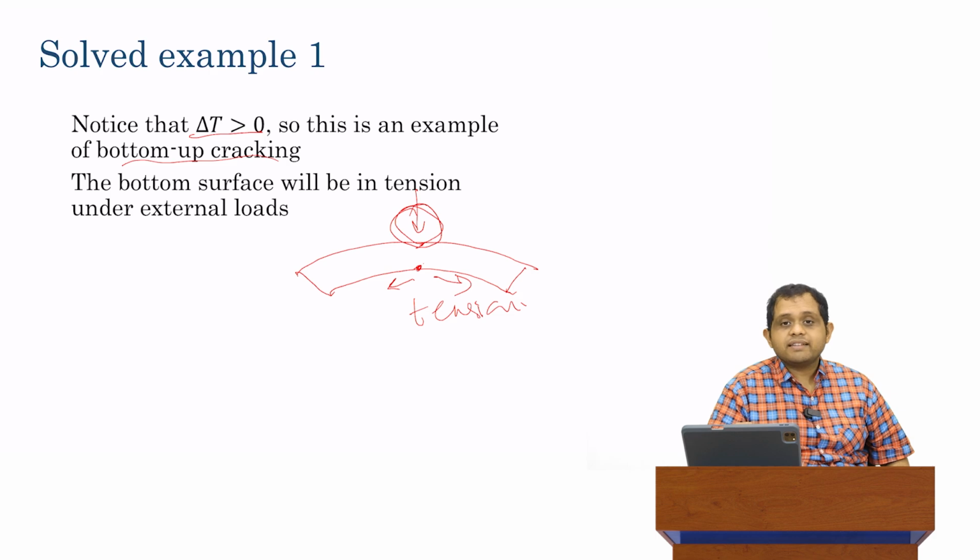We're concerned about the tensile stress, because it is at this point, once the tensile stress exceeds the strength... actually, that's not what will happen. It's based on repetitions and fatigue theory. So we'll talk about that in module 4 much later. But what will happen is, because this bottom surface is at tension, eventually we're going to have a crack that starts to form. It will start at the bottom and propagate upwards, which is why this is called bottom up cracking. So this particular example could lead to a case of bottom up cracking forming under certain conditions of fatigue, which we'll talk about in module 4.